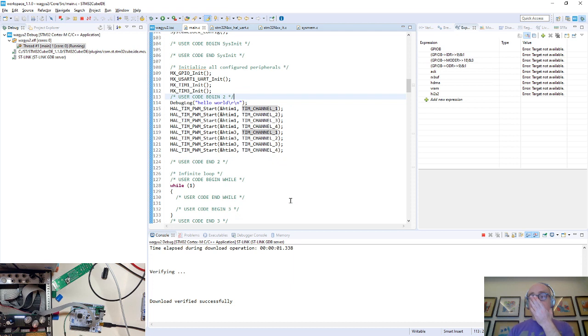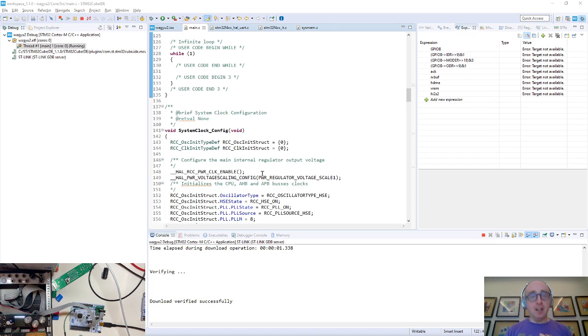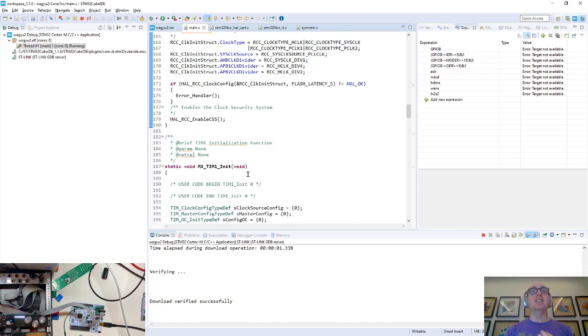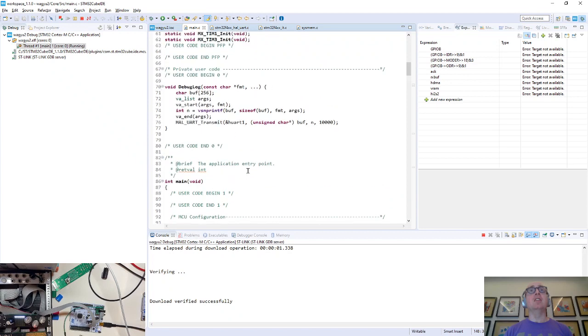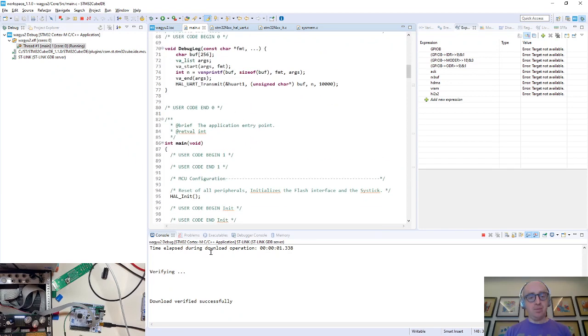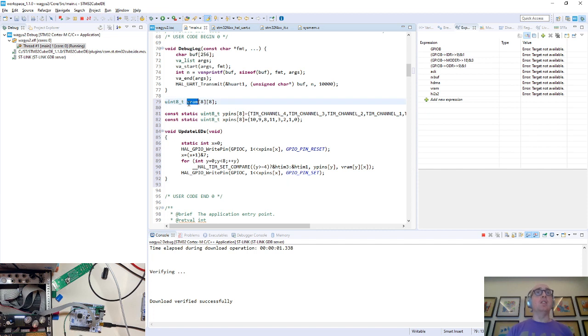Now, we've got to cycle the N pins, right? So I'm going to write this as a little state machine. Are you getting excited? Let's write a little routine called update LEDs, and its job is to update the LEDs 1 row at a time, right? We're multiplexing. So I'm going to accelerate a little by doing the here's-one-I-made-earlier vibe. I'm going to give myself a little 8x8 VRAM buffer, which is going to be our grayscale picture that we're going to display on 8x8 pins.